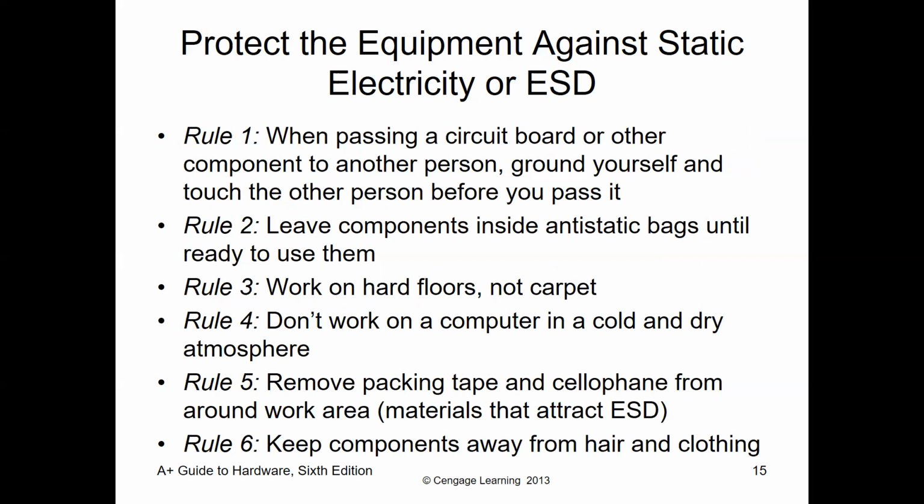To protect equipment against static electricity, or ESD, follow these simple rules. Rule number 1: when passing a circuit board or other component to another person, ground yourself and touch the other person before you pass it. Rule number 2: leave components inside anti-static bags until ready to use them. Rule number 3: work on hard floors, not carpet.